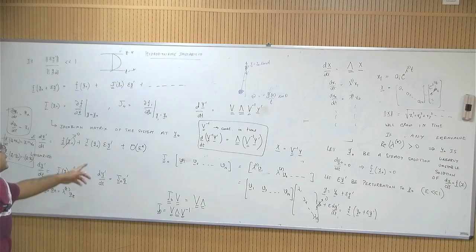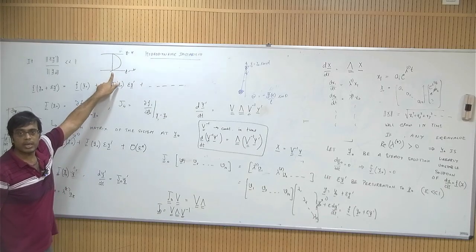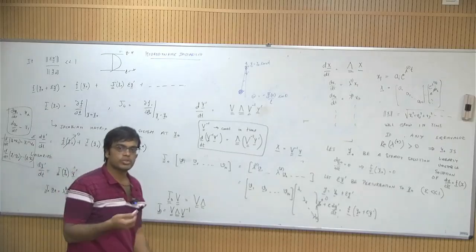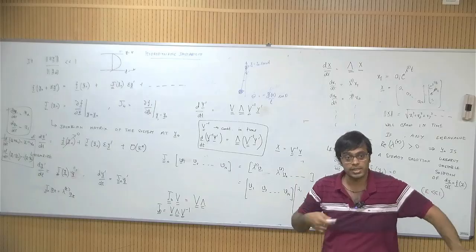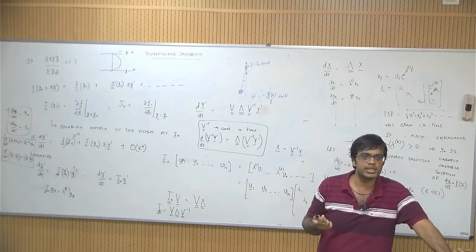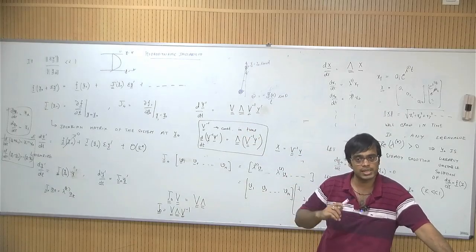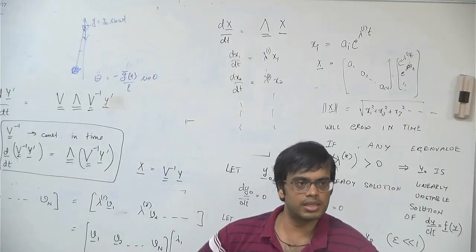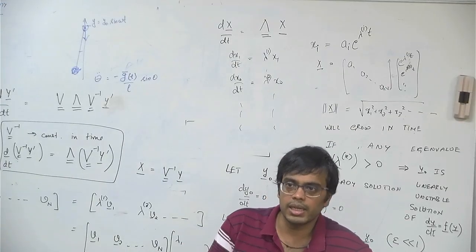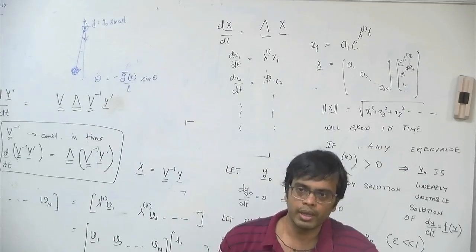You will see that there is a stability regime of this kind of a flow. Okay, and in terms of fluid dynamics, you will see that as you increase your Reynolds number, the stability regime basically changes. Some form of perturbations will grow to infinity after some particular, critical Reynolds number. There is a critical Reynolds number after which you will see that some perturbations start growing to infinity.